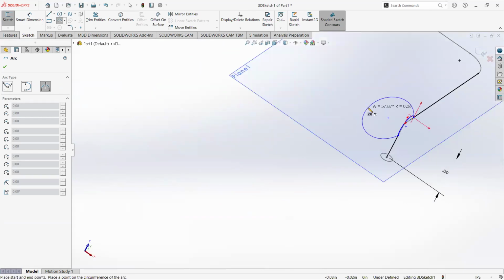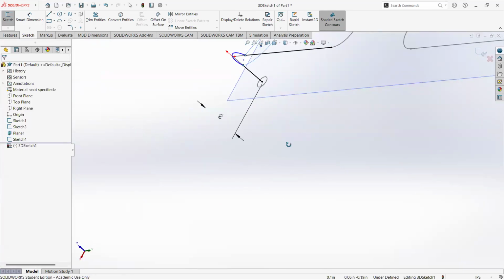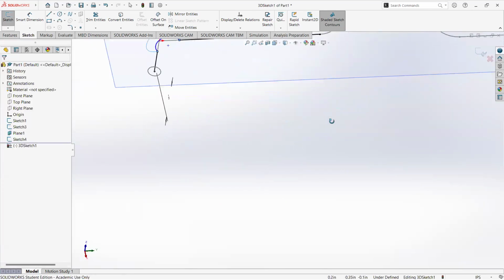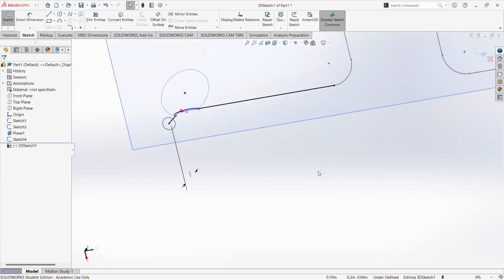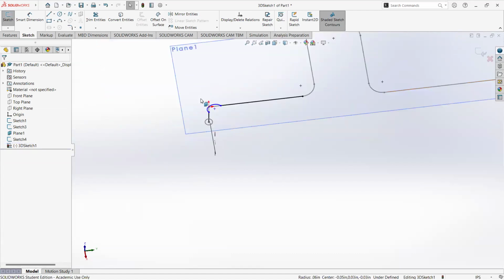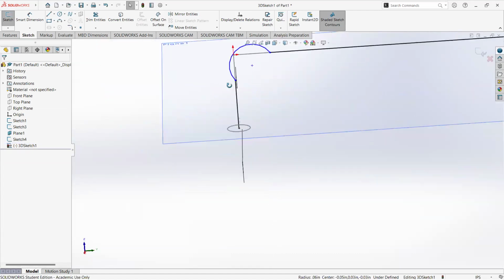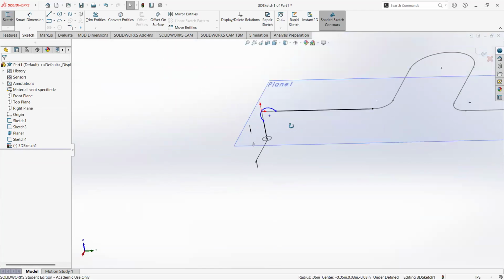Maybe if I switch my view enough. There we go. My view was switched. Notice it drew that second arc way out in a random orientation, right? That is one of the dangers of 3D sketches. So I recommend orienting your model rather than trying to fix a feature like that arc that was way out on a random angle.